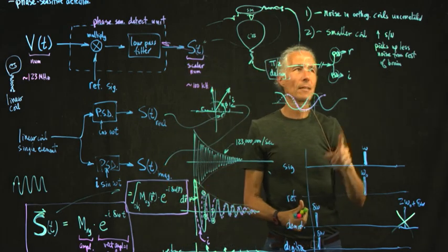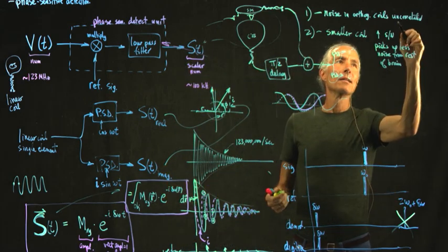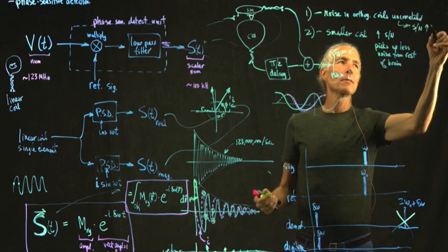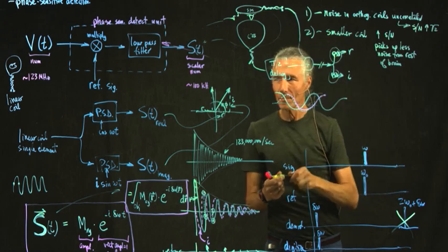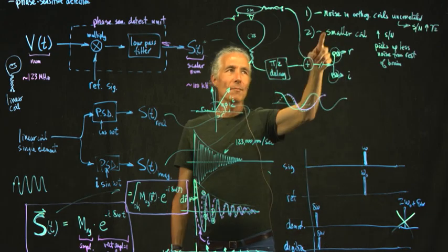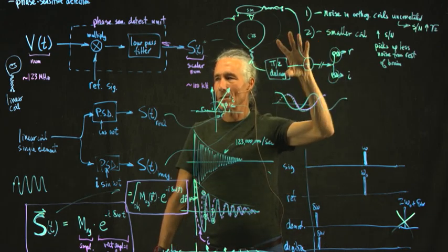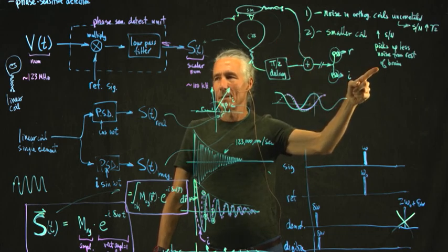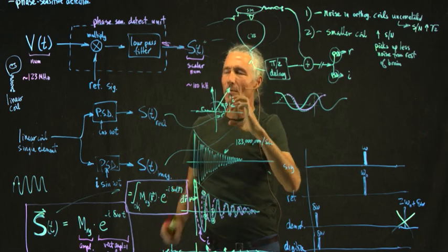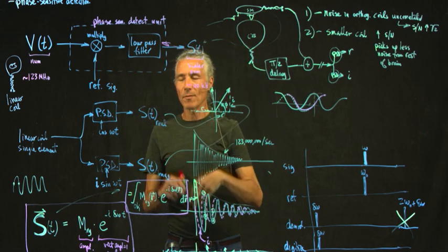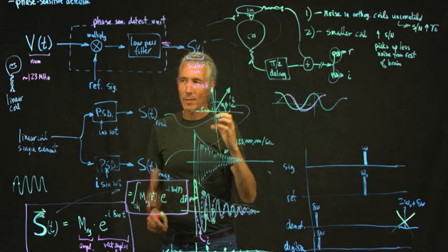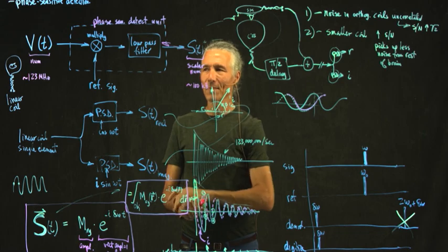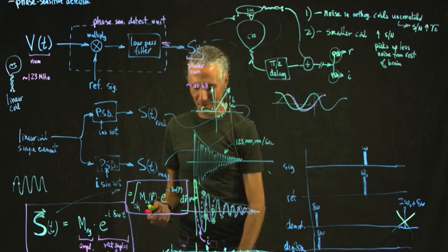And so this is one way. This makes the signal to noise go up by the square root of 2 when you have a quadrature coil versus just a single coil. This other one makes the signal to noise go up even more if you have a whole bunch of small coils, because each one is essentially ignoring noise from the whole rest of the brain and yet getting the same signal from the part of the brain that it's sitting over. It doesn't actually get a bigger signal. It just gets the same signal.